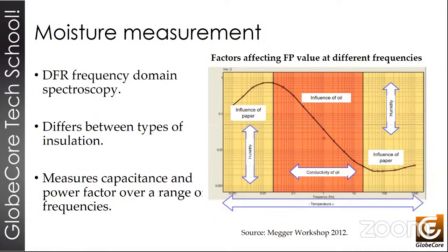Okay, so there is also the FDS, frequency domain spectroscopy, and the results of the analysis show that the real dielectric constant and the imaginary dielectric constant increase with the decreasing degree of polymerization at the low frequency stage, while they remain unchanged at the high frequency part. Increasing the moisture content of the oil-impregnated paper would increase the real dielectric constant at 10^2 Hertz and the apparent dielectric constant throughout the frequency test. So the curve of the imaginary part, together with the increase in water content, will show a trend towards the right. Next slide, please.